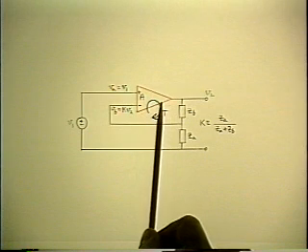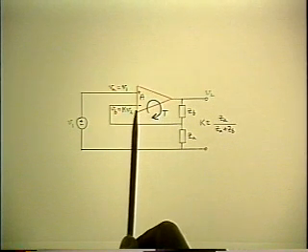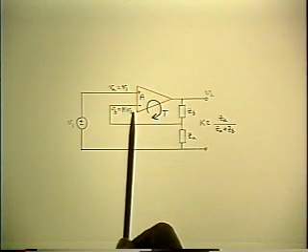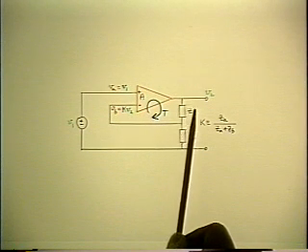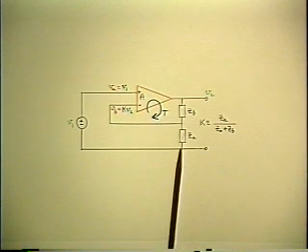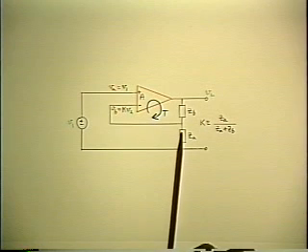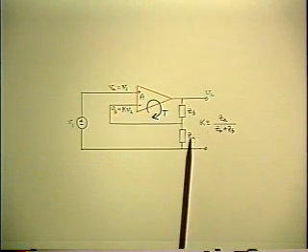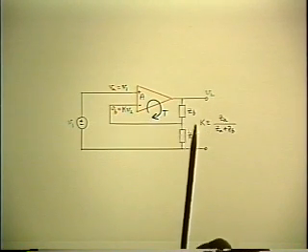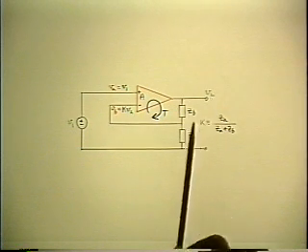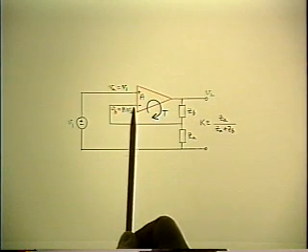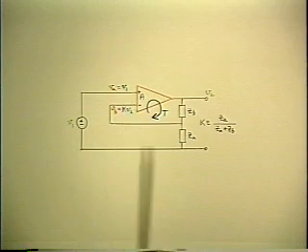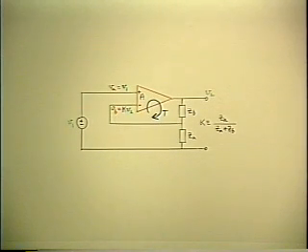It's got lots of gain with a differential input. A very common connection to feedback is you take an impedance divider, which is the K box. So K is ZA over ZA plus ZB. So the fraction K of V2 is fed back to the input. This is a standard configuration. How do you go about calculating the gain of that amplifier?